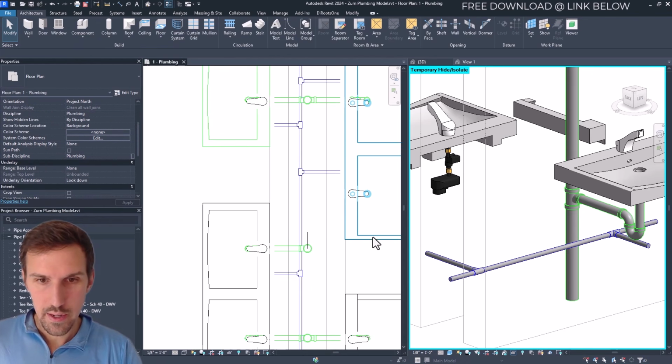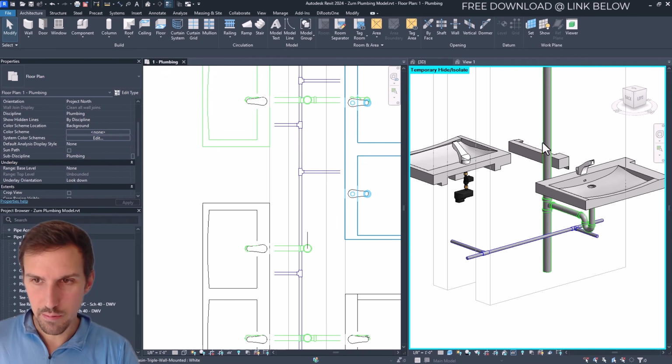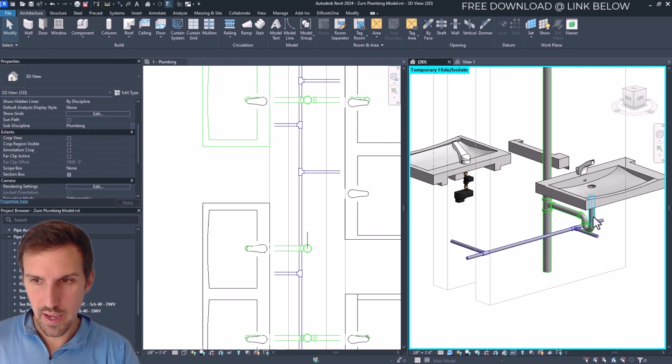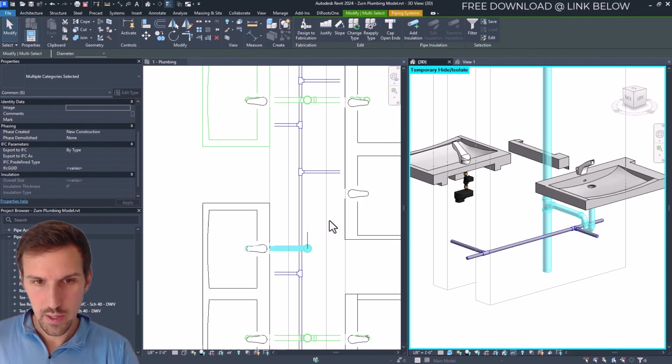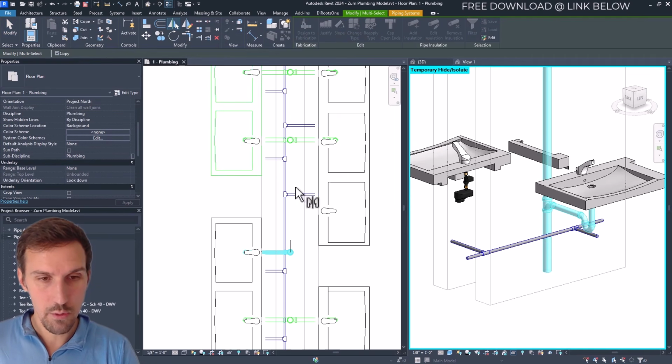That looks great. Now I want to make a copy or a mirror copy of all of this stuff right here. So all I have to do is tab into it, click, and then I'm going to click into my floor plan. And this time let's use the mirror pick axis because we have this little axis right here. We're going to click on this one. And you always want to make sure you have copy if you're making a copy. If you're not making a copy, make sure you deselect that. So I'm going to click it.